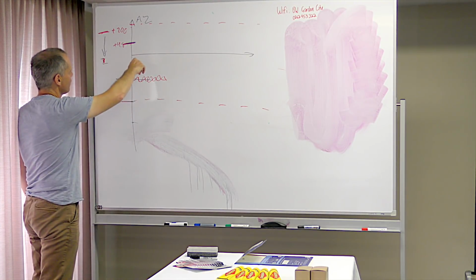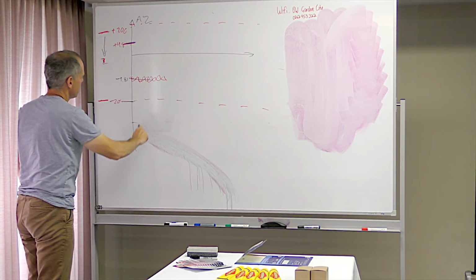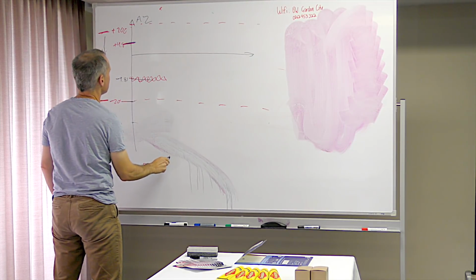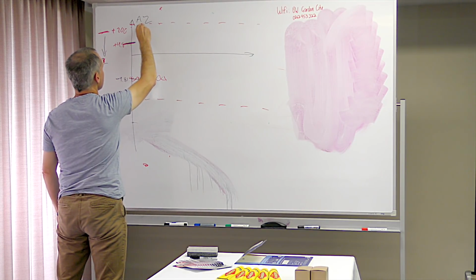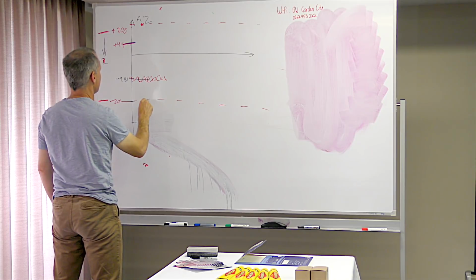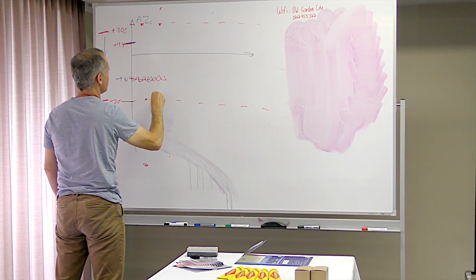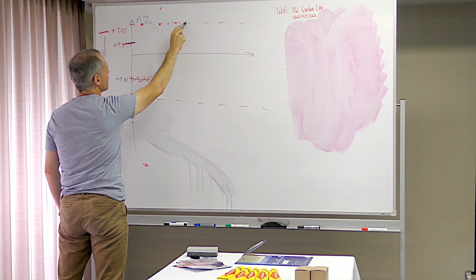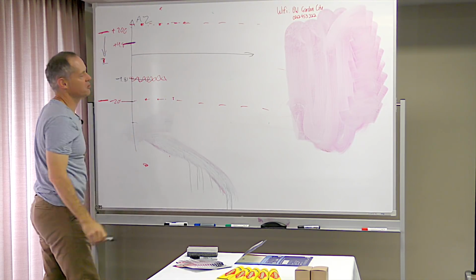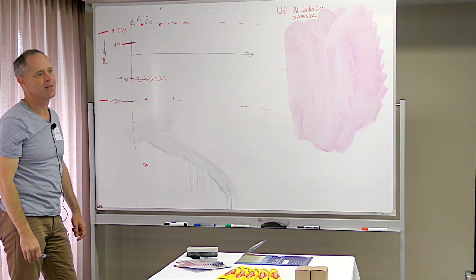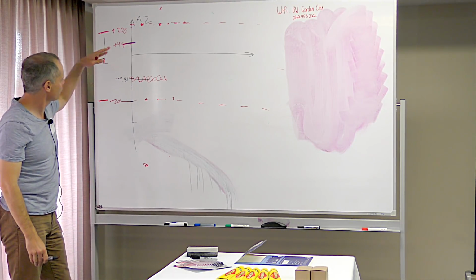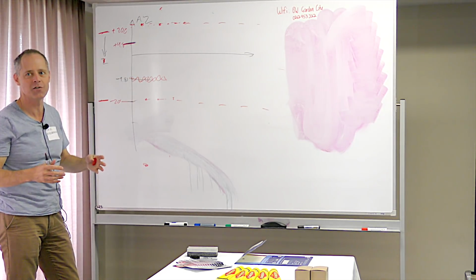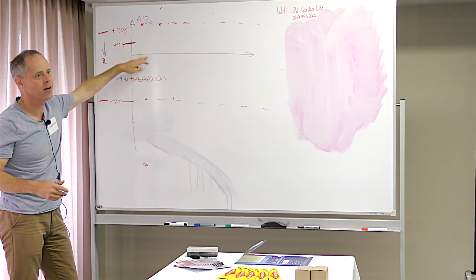What happens as I start to throw this thing into saturation, I have a measurement down here and a measurement up here and a measurement down here, is that it ends up flipping. And what you end up getting is measurement, measurement, measurement, measurement. In other words, most of your measurements are starting to sit at your clip limits, which is symmetric around about 0. So what happens when you throw a huge amount of vibration at your vertical accelerometer is that the average value starts to tend towards 0.